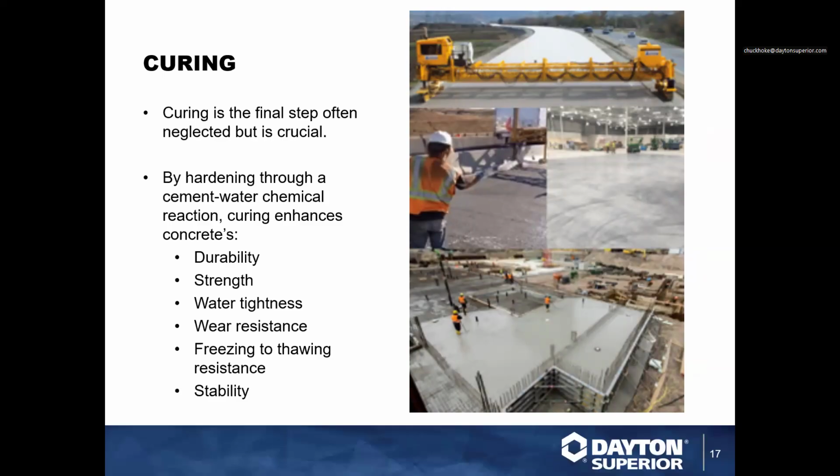Curing. Everything you do here, placing the concrete, putting it in place, is a result of a process. And when you finish off the concrete, you have to ensure that you're not going to damage the surface of the concrete by letting too much water evaporate off the surface, basically sucking the moisture out of the surface, which will cause crazing cracks within the concrete mix.